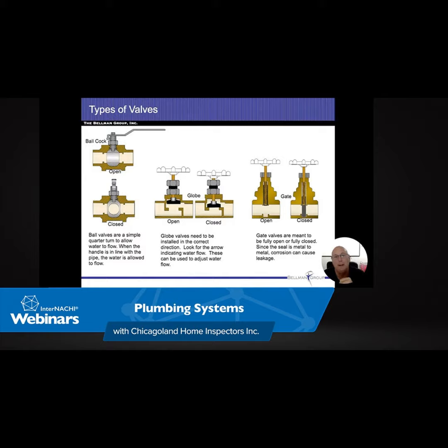So as the cold water comes in, the cold water pipe, we're going to drop down to the dip tube. All right. So you can see the blue water line goes towards the bottom of the tank. So as cold water enters the tank, it's going to enter at the bottom. Naturally, heat rises, so it's always going to be the hottest at the top and the coldest at the bottom.